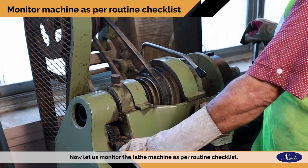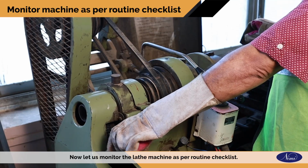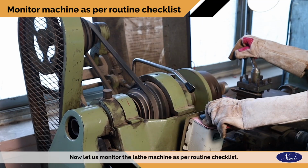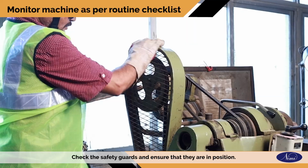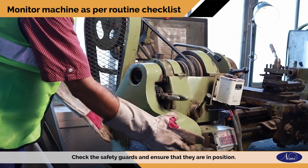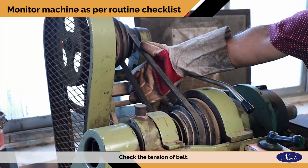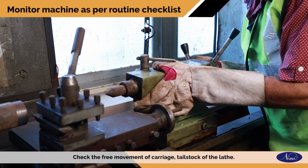Now let us monitor the lathe machine as per routine checklist. Clean the machine, check the safety guards and ensure that they are in position. Check the tension of belt. Check the free movement of carriage, tailstock of the lathe.